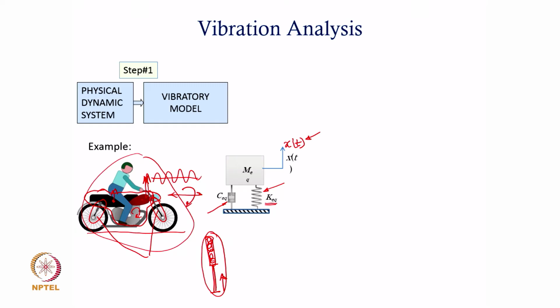So, obviously, as you would agree, you will have to have, apart from all of these, the possible forcing functions or the excitation mechanisms on the structure. So, maybe I will specify that forcing function as the force. Where would it come from? This system, even if it is stationary and standing idle, but the engine running, we know that it vibrates. The vibration essentially comes from the engine. So, from the engine source, if I somehow characterize what forces are generated in the engine, then I have a forcing function that is going to act on this chassis and therefore, on the mass m equivalent.